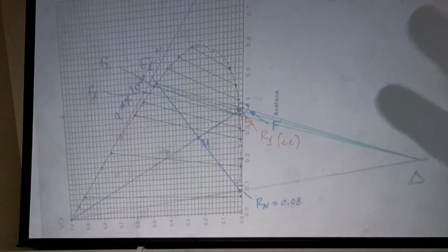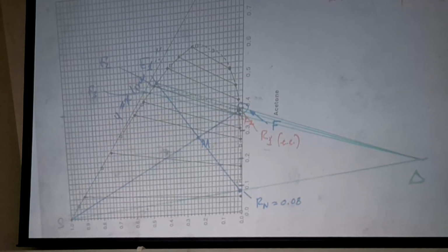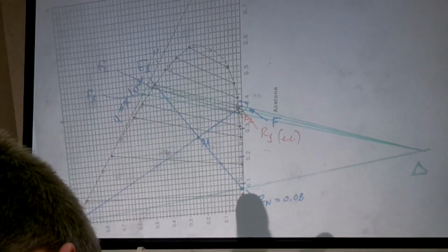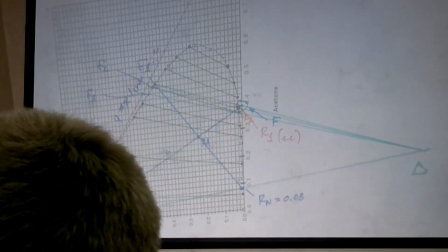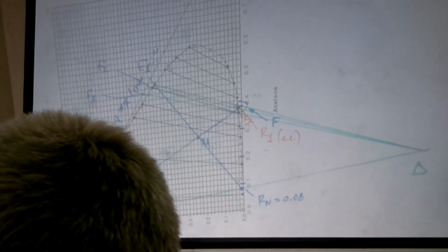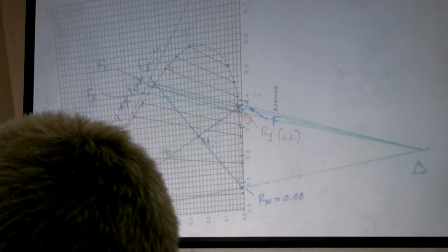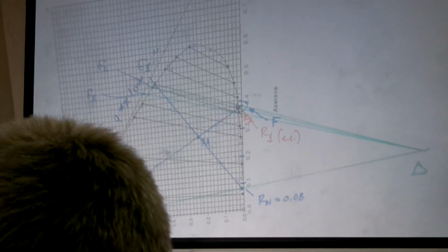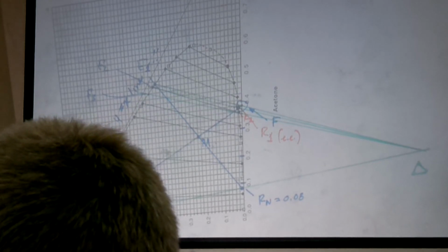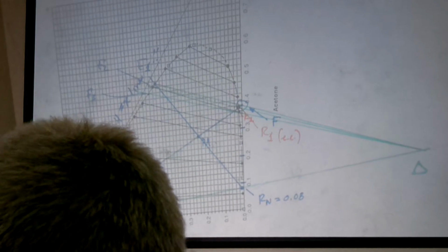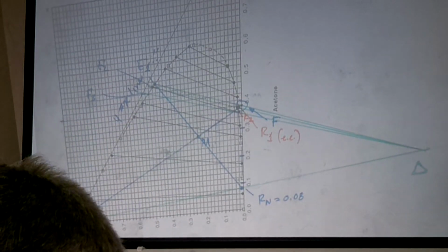So we continue this process, working our way back and forth between equilibrium and operating lines until what? Until we get tired? Hopefully before we get tired, we hit Rn. You think you're going to hit Rn right on the money? You might, depending on how good you are at fudging your line. Just like in McCabe-Thiele, though, it doesn't matter. In McCabe-Thiele you get fractional stages. In liquid extraction, you get fractional stages.